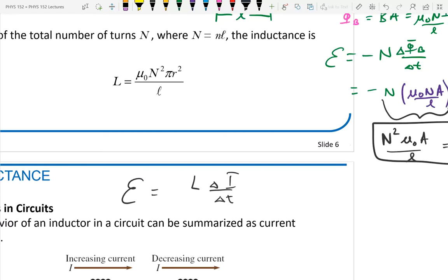It was there to remind us to look at Lenz's law to determine what direction we were going to make the current. And for an inductor, if you wrap the wires to the left, you're going to have a different magnetic field direction. If you wrap them to the right, you have to apply Lenz's law to determine how things are actually going to play out.